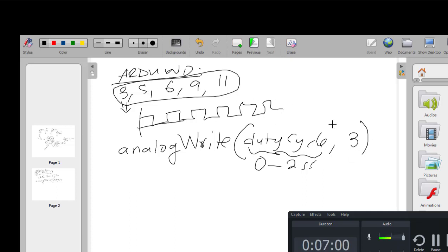And now when you do that, it means that the pulse width, what is this pulse width? So if this is our period, the relationship between the period and the T on, so T on over TS, this is the T on portion times 100%.